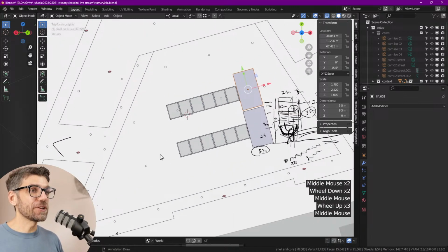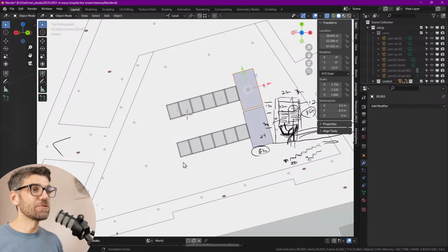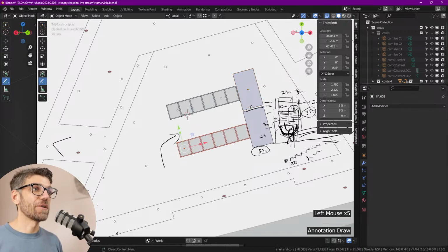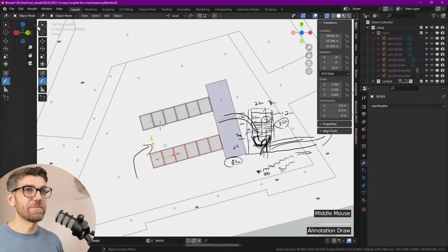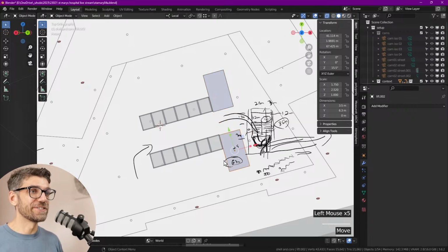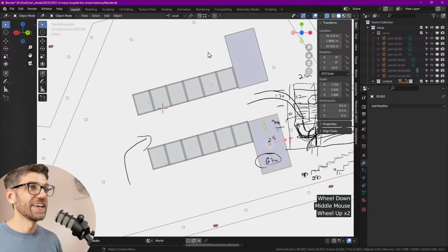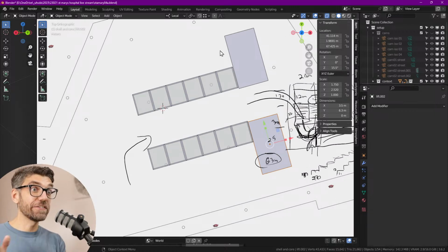Okay, so I think this is pretty good, except I feel like that's a tight spot, right? To only move people from one side here. I would ideally like to have a double kind of open circulation. And what does that mean? So we should move that core out that way and that core out that way. And you see just the cores, right? They get massive, and that's covering a good bit of our floor plate. Besides that, we would need some extra rooms in there, some extra shafts, especially in a hospital.